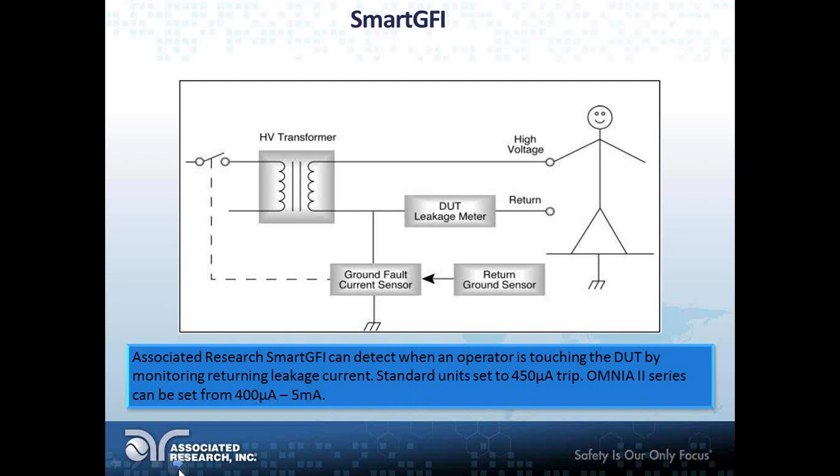I've put the return lead in the proper spot on ground, and I will push the test button while holding it, and the SmartGFI trips before I can even feel anything. Number one, please don't do that. I am not advising that you do that. I am a trained professional when it comes to Hipot testers, so just like you see at the beginning of a Jackass video, do not try this at home.